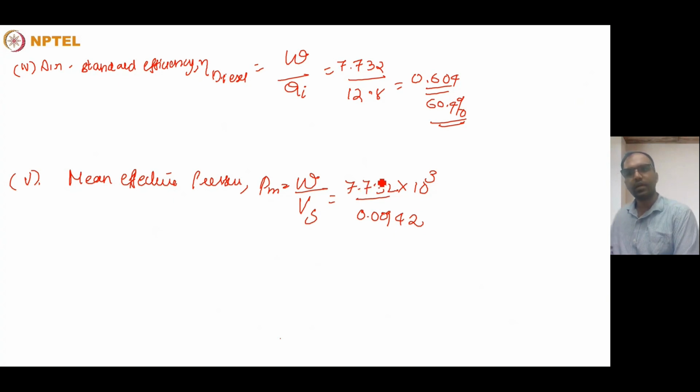So it doesn't require the correction factors which we have used in the previous problem to convert from revolution per second to cycle per second, where we divide it by 2. Here it is not required since it's per cylinder. It's a kg value per cylinder. It's a volume value per cylinder. So the mean effective pressure will be 8.21 bar.